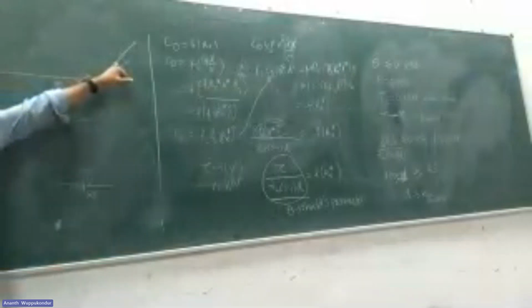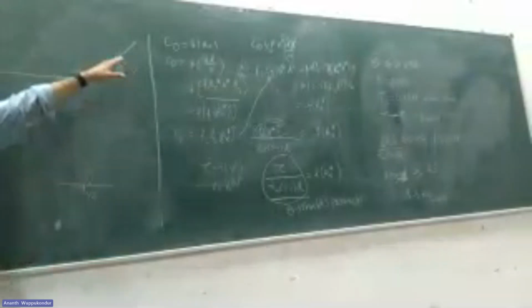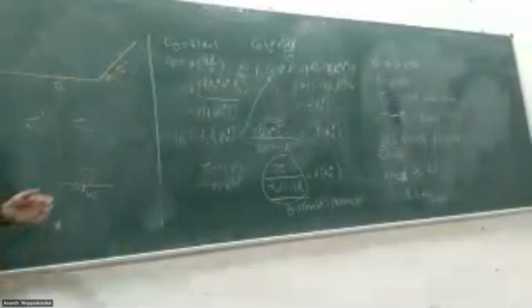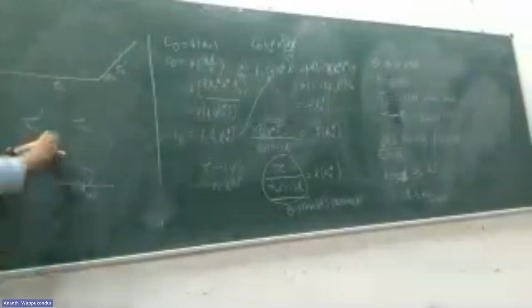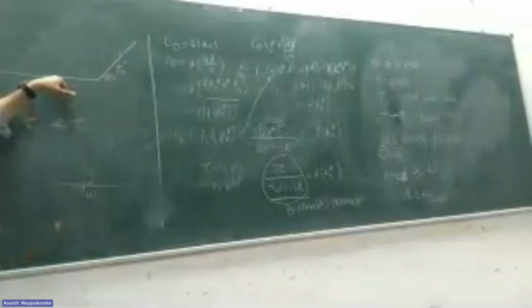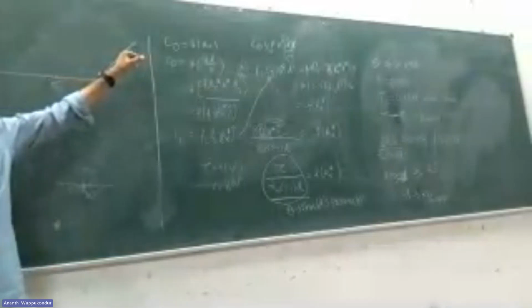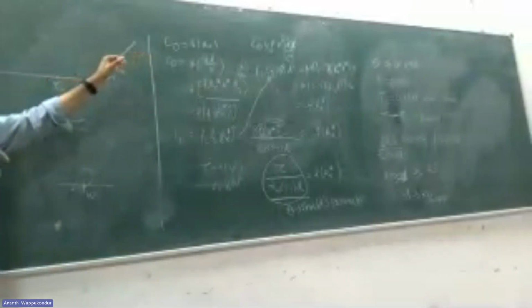What about on the slope? You would have some weight component that is trying to disturb the sediment. So yes, if you compare the shear stress required from the flow, that would be less than the shear stress required on the bed. So the flow does not need to put much force on the side slope because the weight of the particle itself is trying to disturb the particle.